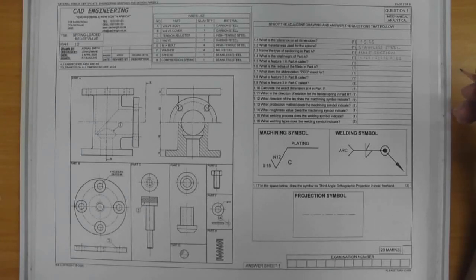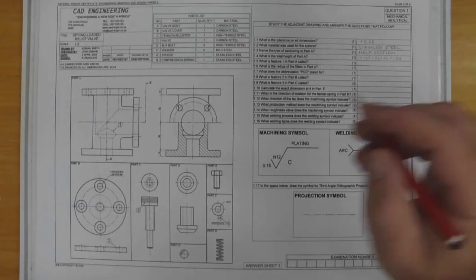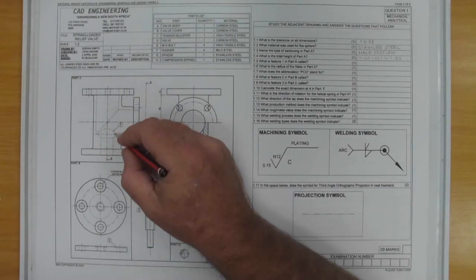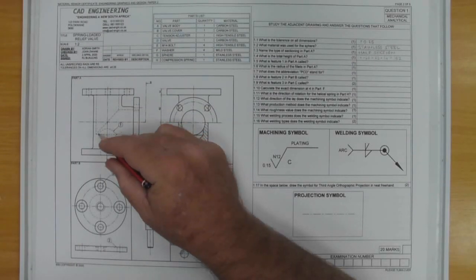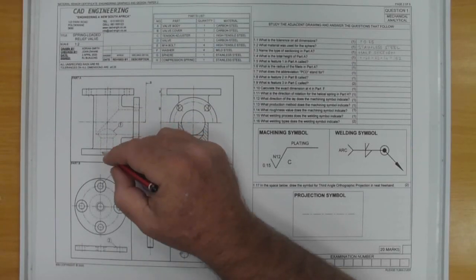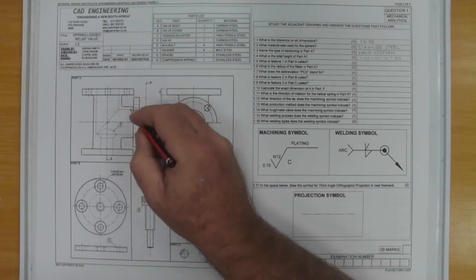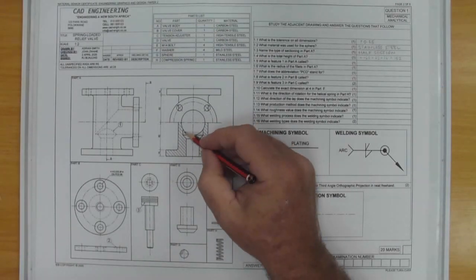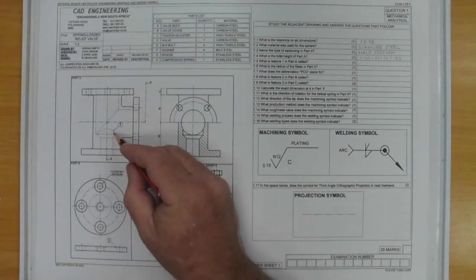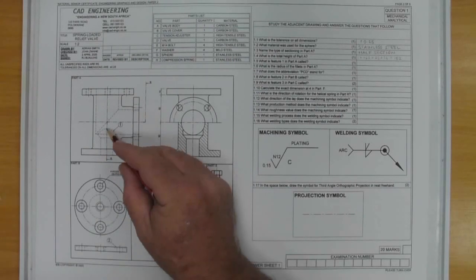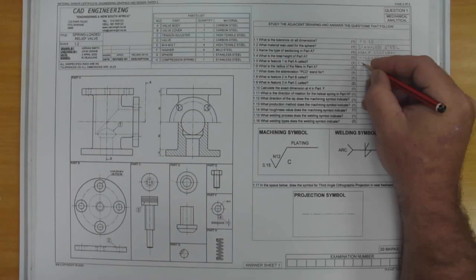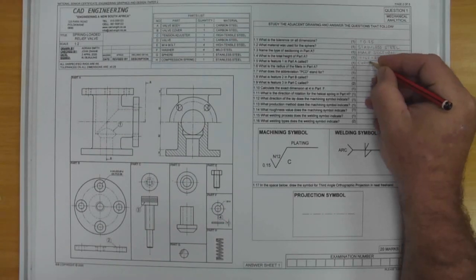What is the feature 1 in part A? Here is this feature. This is the correlation between your understanding of paper 1, which is showing how this narrow pipe is fitting into the bigger pipe. So this is the bigger pipe, here was the smaller pipe, and it creates a funny shape where they join each other, which is called the curve of interpenetration.